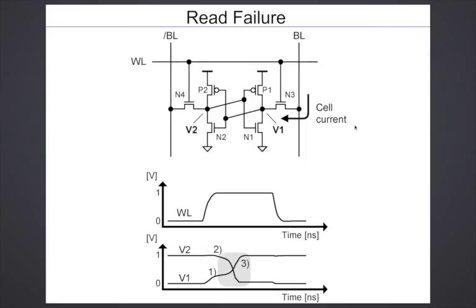Now one thing you have to remember is that when I say you can't get SRAMs to work at those voltages, you might have a single cell in the typical corner working fine. Okay, it can probably go all the way down. But if you recall, with SRAMs you want to pack as many cells as possible because more memory is always better for your application, which means the sizes used in these transistors are all minimum size, which means they are really exposed to a lot of process variation.